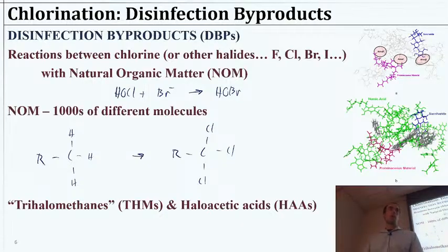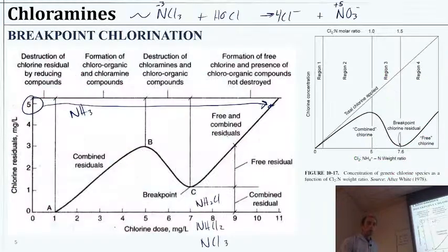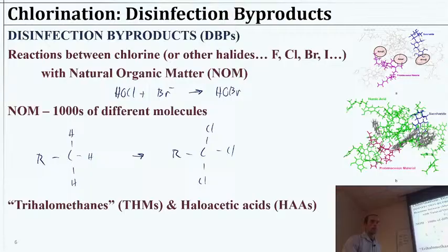So if we can get rid of our dissolved organics, have some pre-treatment, perhaps then we will mitigate how much of these carcinogens we have in the drinking water, right? So either way, we can design our system to function with a smaller residual, more time, but a less highly oxidizing environment, which could be a way to mitigate these disinfection byproducts, or have fewer dissolved organics.